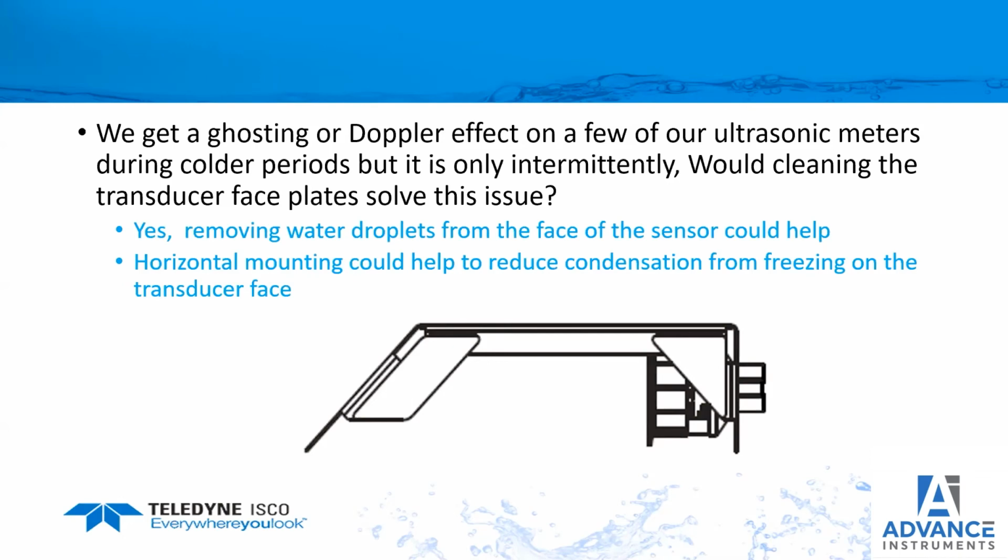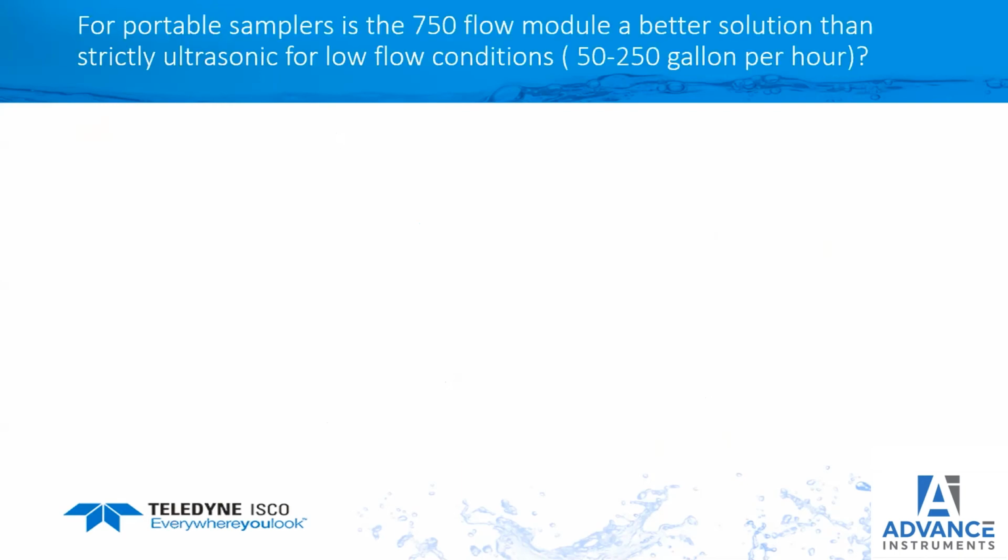So one thing you can do is we sell a horizontal mounting bracket. And so if you mount it horizontal, now those water droplets should go to the bottom of it and stay away from the face of the transducer. So that could help minimize that problem.